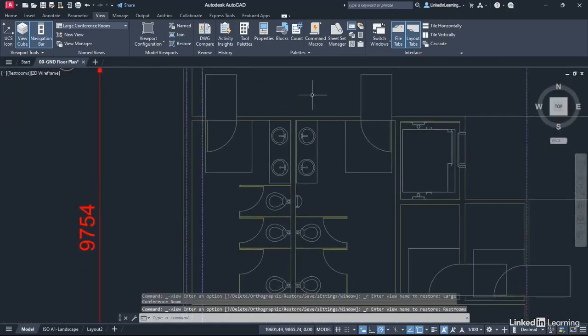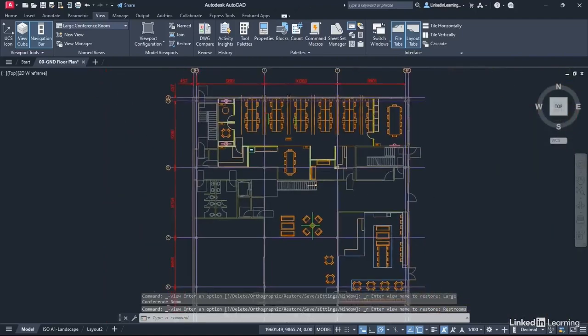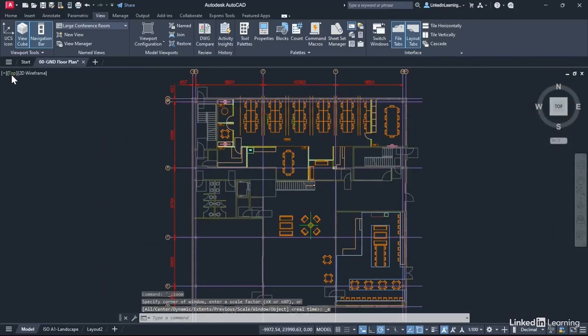And then if you double click on the wheel again to zoom extents, you'll notice that view control goes back to top, like so. The preset top view. So as you can see there, those named views are an incredibly useful way of getting around large area drawings when you've got lots of things going on in your model tab and your layout tabs in your AutoCAD drawings.